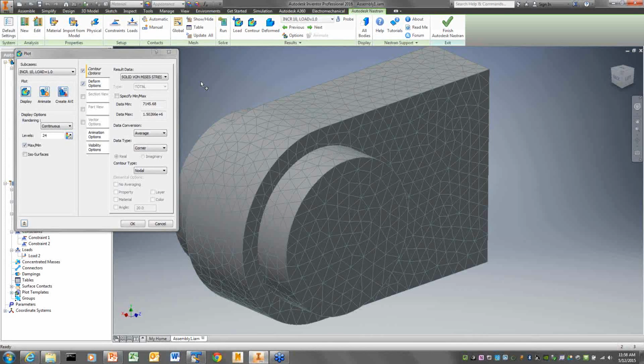I believe those forces get generated whether you ask for them or not. That was an Autodesk Nastran thing. I don't know that you've run across this, Andrew, but I don't believe you even have to ask for forces in order to get that. No, I think it generates it automatically. Yeah, in my experience, it'll generate that information automatically.